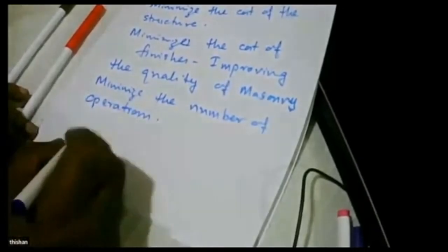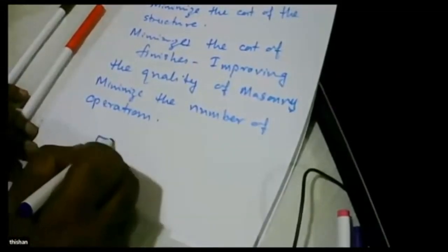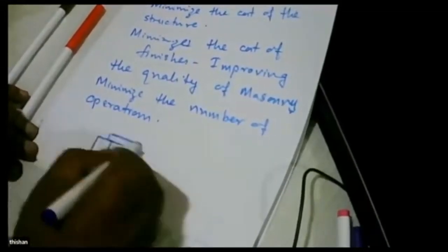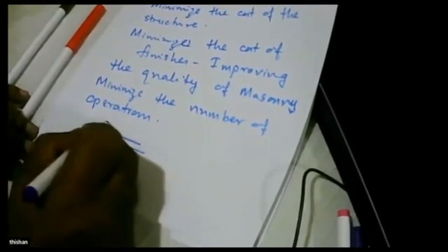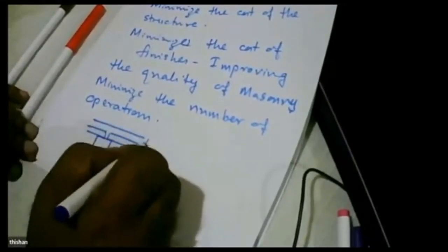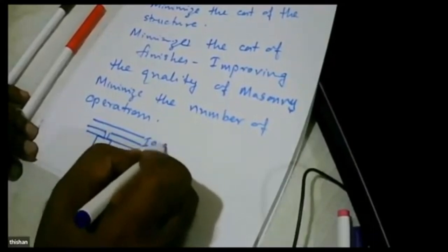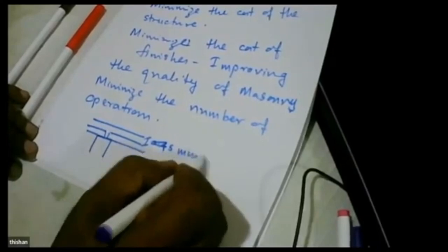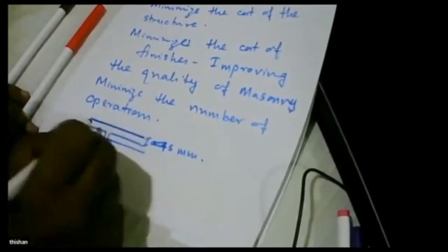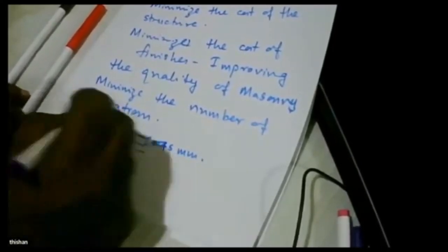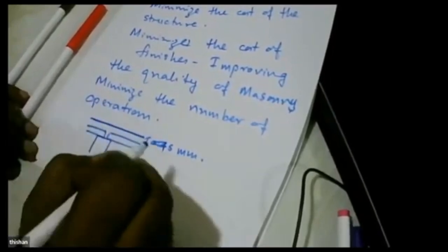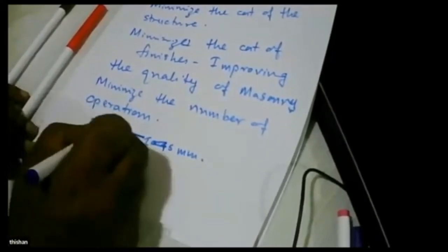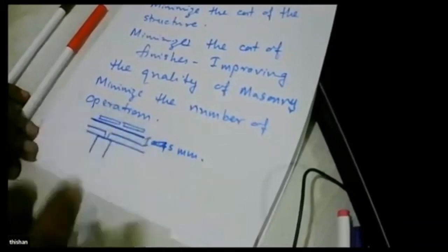So that's where I told you that when we are laying this, because we are doing only a thin concrete, 45 millimeters, we can do it slowly and make it a good finish, so that the tiles can be laid directly on this.